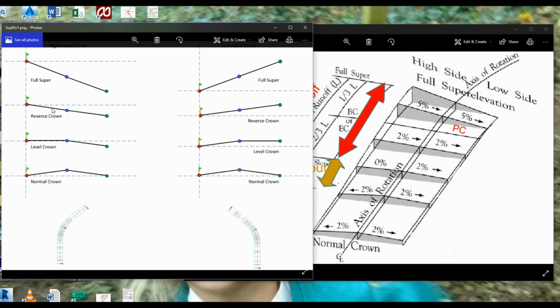We've got a continuous cross slope of 2% going there. And then we would carry on until we reach full super elevation. Okay, we would go round the curve in full super elevation, keep going round until we get to the end of full super elevation. And as we come down, it would be the exact opposite of what we would have going in as the ramp in for a full super elevation.